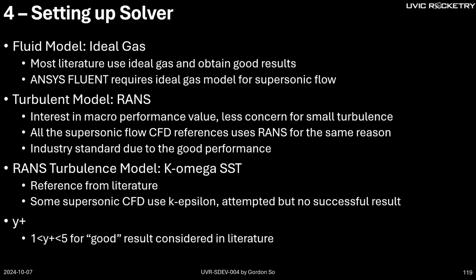For the Y plus, around this range is good for boundary layer resolution. I did not really achieve it for most of the simulation. You will see why when we go down to the slides. It's just a fight with the mesh.